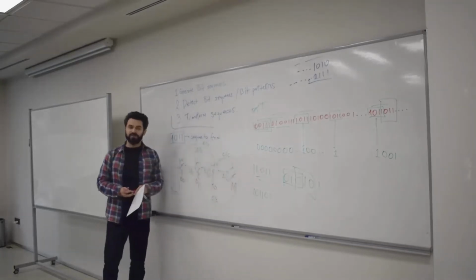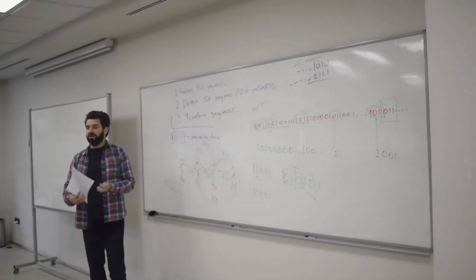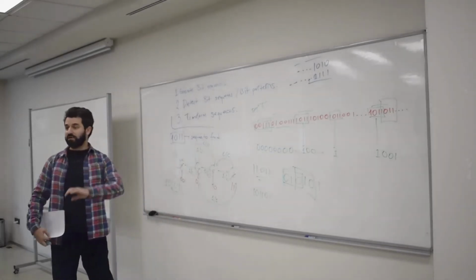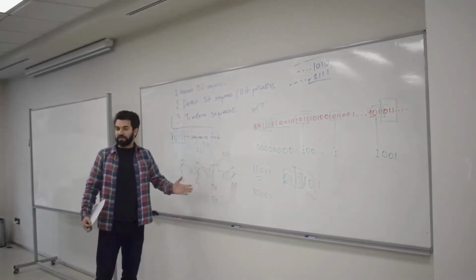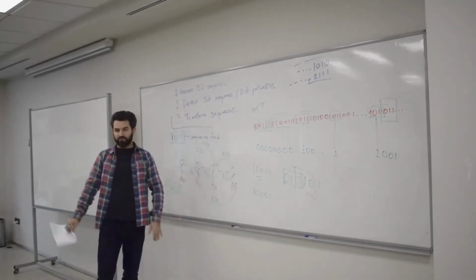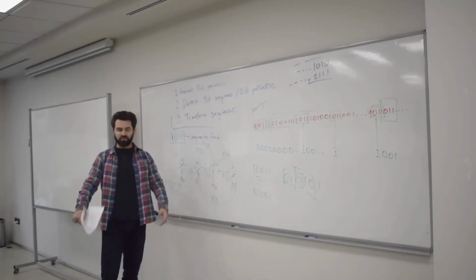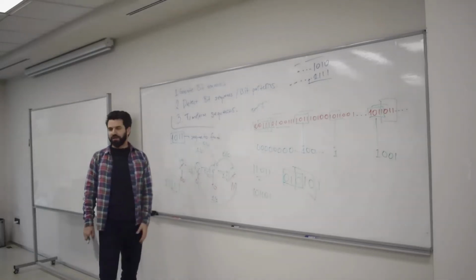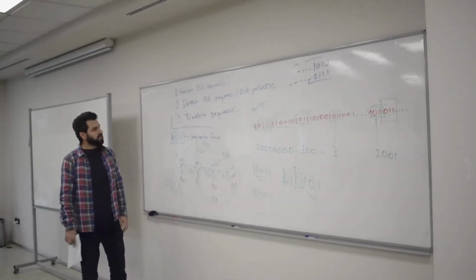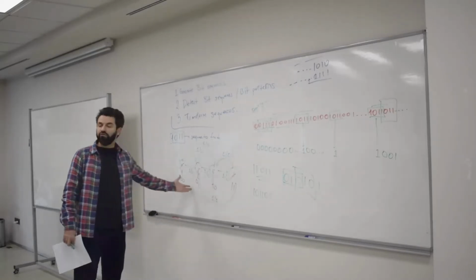Simple. As I said, alternative mappings are beyond the scope of this class. It requires a lot more expertise to cover and master. So I'm just going to apply the simple approach of minimizing the number of registers in my circuit. I'm going to have only 2 flip-flops here.